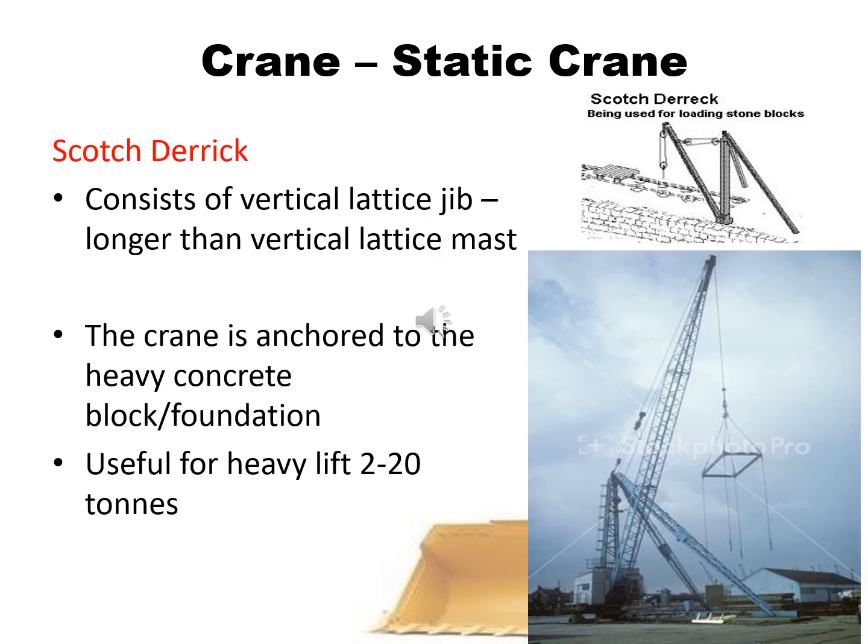Another example for static crane is Scotch derrick. It consists of a vertical lattice jib, which is longer than the vertical lattice mast. The crane is anchored to a heavy concrete block or foundation. It's useful for heavy lifts of about 2 to 20 tons. Scotch derrick is being used for loading stone blocks.